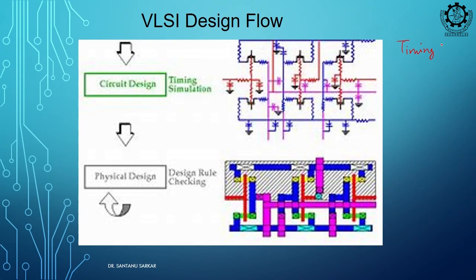So, timing analysis. When you are doing RTL, you are considering ideal gates, right? There is no transport delay or path delay. But in reality, you have to check all the path delays, all the RC delays. So your analysis, apart from the gate, will consider its self capacitance and wire resistance, and the simulator considers all of these and gives you the realistic analysis.